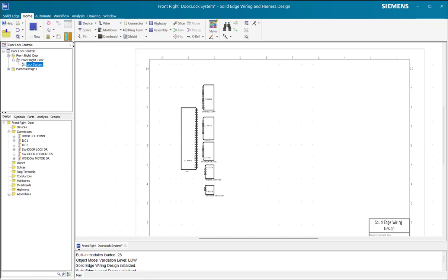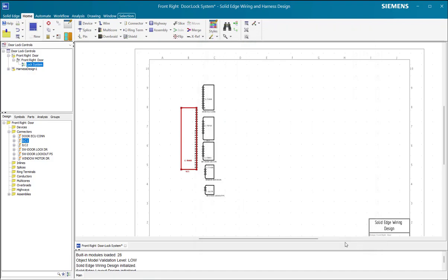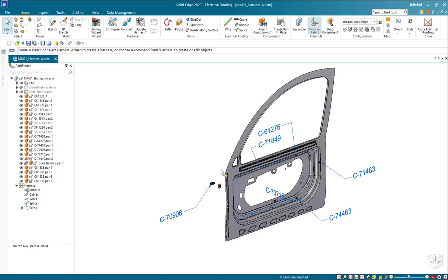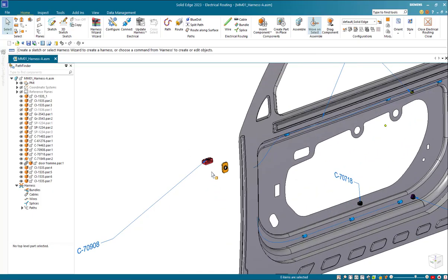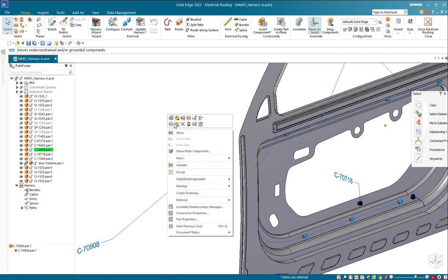One of the things you need to do first is make sure that the numbers match the part numbers. So if I go look at this one right here, you can see that obviously there's my library part number. There it is right there. And we need to do that same thing on the CAD side. So let me go ahead and show you that needs to be done up front. The one I'm looking for is this guy right here, so I'm gonna go ahead and open that up.